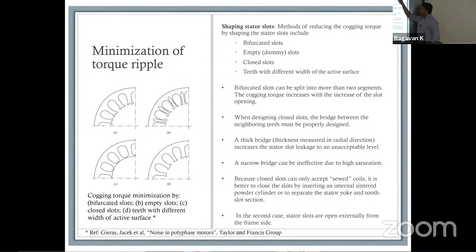Yeah. So you can do the stator slot shaping. You can actually shape it to a place where, if you remember field reconstruction that I had talked about before, that was one of the objectives, that we would look at the field distribution inside the machine and start changing the BN and BT, because what's happening is that acoustic noise basically goes into the slot, and that causes your motor to have a certain kind of noise. Has anybody here heard of a Helmholtz resonator?